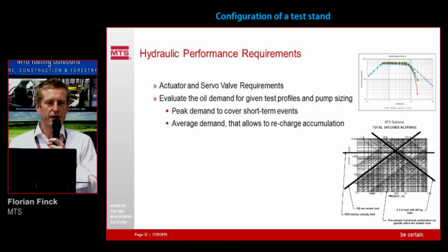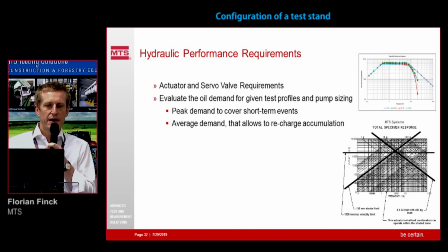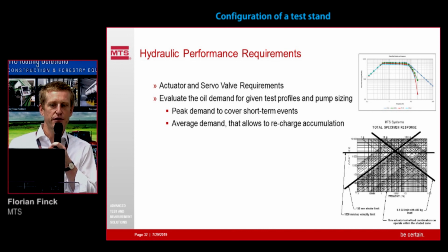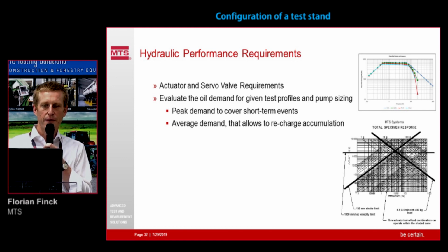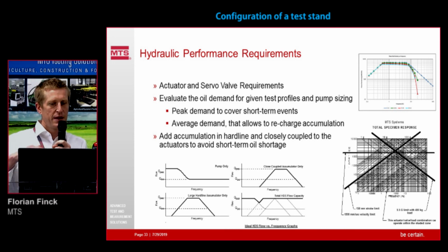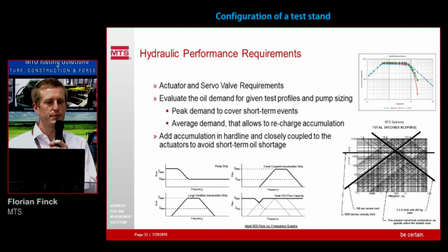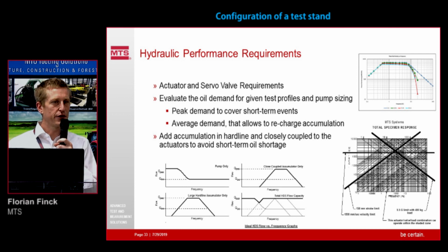The oil demand can be derived from the test profiles that you're providing, the pump sizing. There's a peak demand to cover short-term events, and then there's an average demand that allows to recharge accumulation. Steve has been talking about that. Accumulation is very important. Again, as Steve said, you need accumulation in the hardline, and you need closely coupled accumulation very close to the actuators to equal out the variations in the oil demand in the complete laboratory.